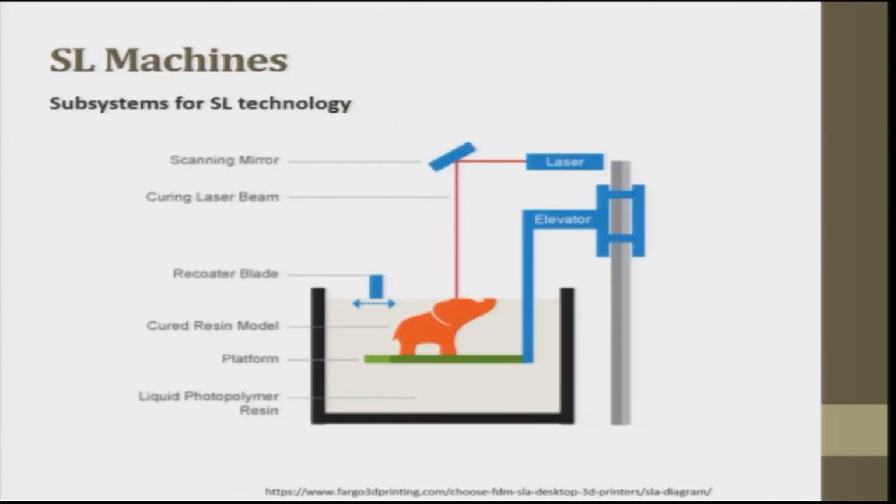So, this we saw in detail in the previous system. So here we are only seeing the new thing, which is the pre-coater blade. The pre-coater blade tries to push the liquid on top of this layer when it is getting formed, so that you have a uniform thin layer which is getting formed. Now which dictates the layer thickness, or how small can the layer thickness be? Generally the layer thickness depends on the resolution of the elevator. So this resolution primarily dictates the layer thickness.